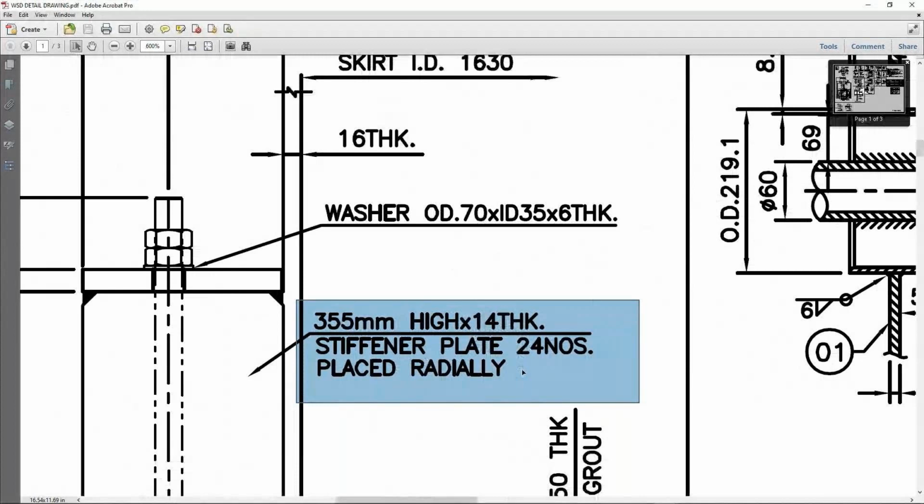And you have the ability to add 4 segments for the skirt. If we take a look at the image here, you can add, as you can figure, 4 different courses, and you can control the thickness of each course, the material of each course, and you can change the longitudinal welding line orientation and control the number of welding lines per course.